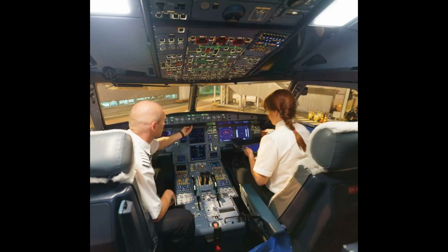Automated flight controls require you to study and learn the system's programming and mode selection actions. You must also learn what actions disconnect the autopilot, whether commanded or not. In pre-flight planning, you must determine the limitations on the autopilot and what the installation in that aircraft permits. It is important for you to be aware of what functions are automated and what activates those functions, and the actions or conditions that cancel or inhibit those functions.